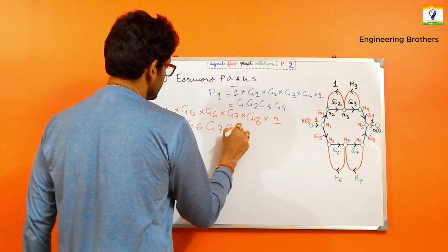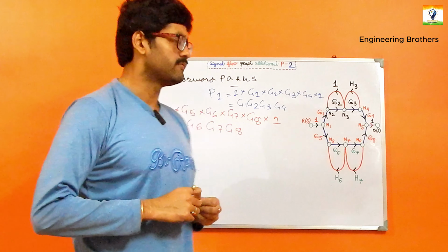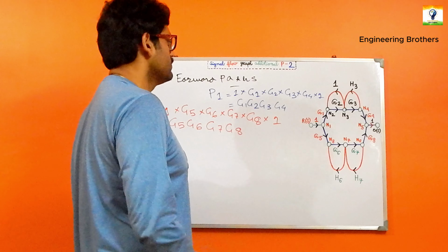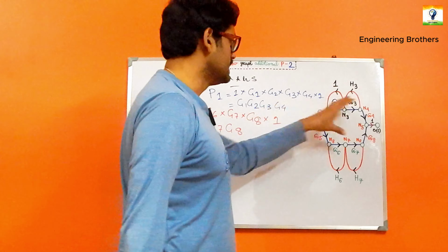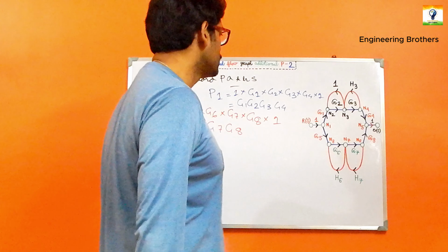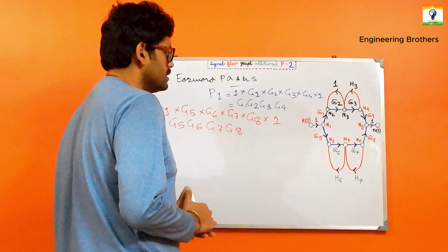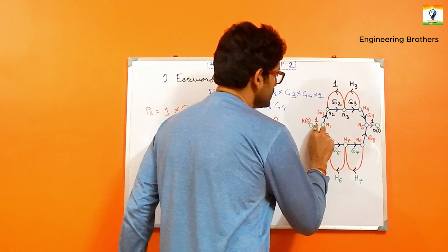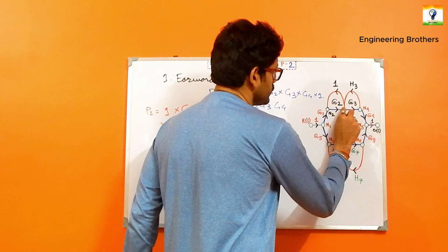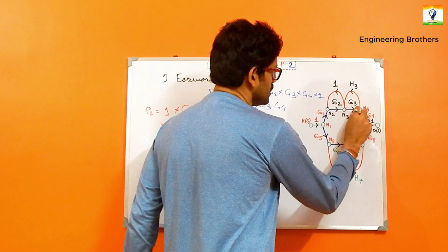Now the first part has been considered, and after looking at this signal flow graph, I can see that there are no other forward paths. Only two forward paths are available. I'm going to repeat this portion once again. You can see that from R(s) to N1 to N2 to N3 to N4 to N5, and from N5 at the last point we have C(s).